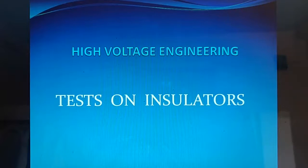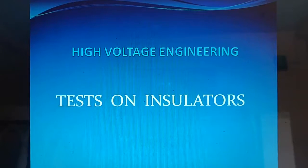If the insulator has any weak portion due to a manufacturing defect, then it will break from that weak portion when mechanical stress is applied on it, and the mechanical stress is applied by the conductor. These are the main causes of insulator failure.